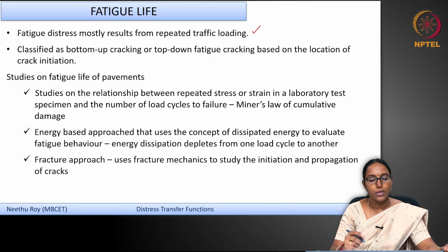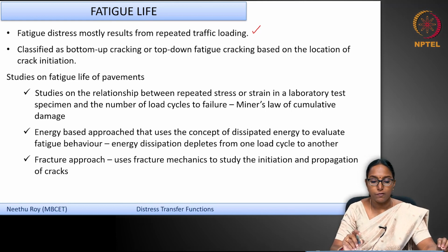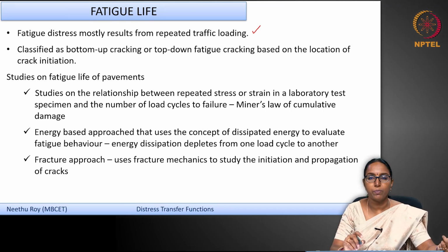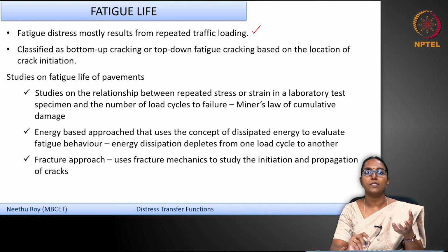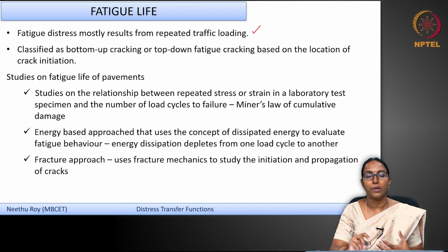Okay. Now, the cracking that you see on the surface could be a bottom-up cracking, or it can be a top-down cracking based on where this cracking has initiated. Okay, whether it initiates from the bottom of the bituminous layer and propagates up, you call it a bottom-up cracking, or if it starts from the top surface and propagates down, you call it a top-down cracking.